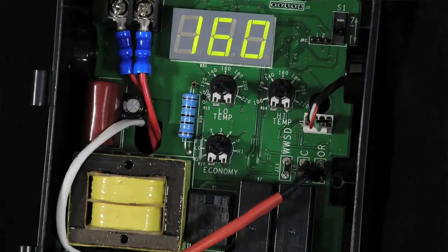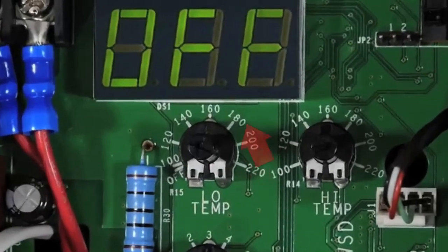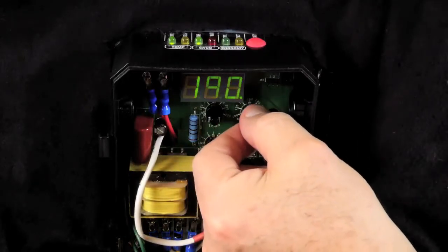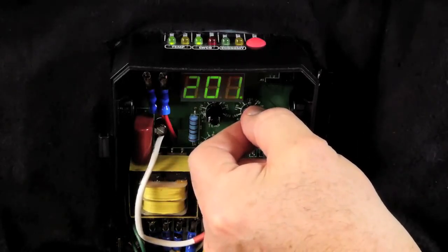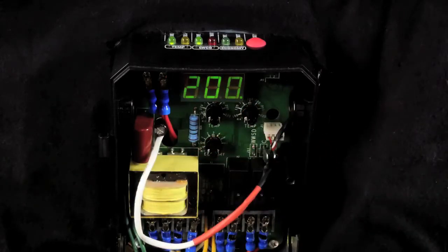If your boiler does not have a tankless coil and will be used for heating only, this dial should remain in the off position, factory setting, which is fully rotated counterclockwise. The high limit is factory set at 190 degrees Fahrenheit. To adjust, turn the high temp dial until the desired setting is displayed. The range is 100 to 220 degrees Fahrenheit.